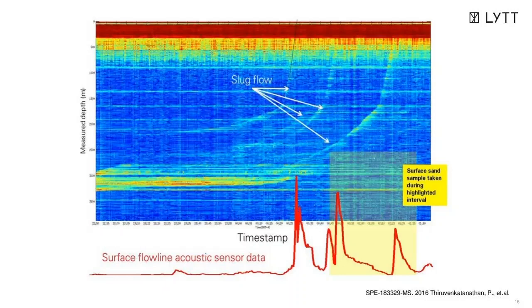And then at an optimum rate, what you see is that the accumulation has disappeared. So now the rate of the well has been increased enough that the well is cleaning up. Basically, it's no longer accumulating sand downhole. And at the same time, in this case, it's not producing sand from the reservoir. So this sort of optimum operational envelope is something you can design based on the insights of this real-time DAS capability. And therefore, you don't defer production as a consequence of sand problem.